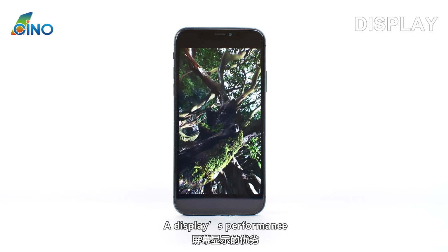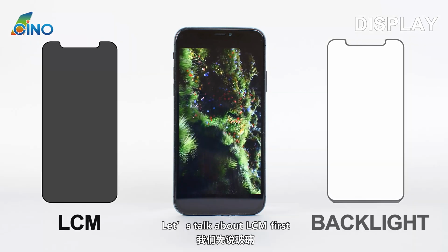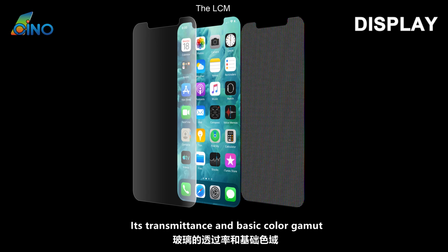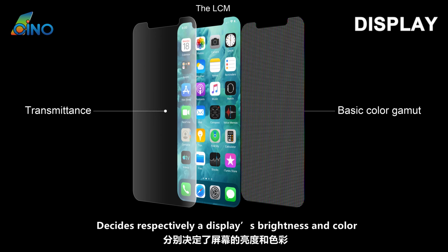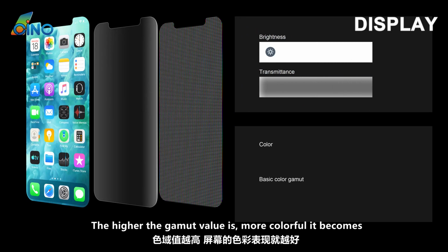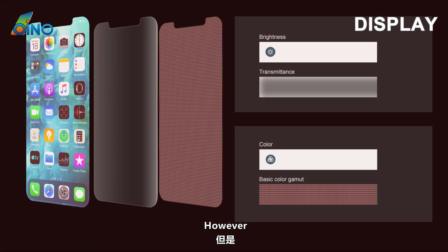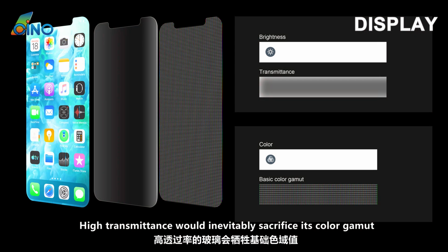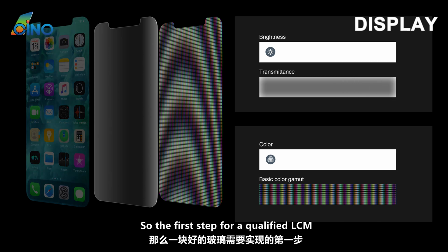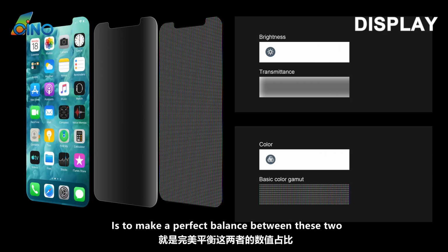A display's performance depends on two major factors: the liquid crystal module and the backlight. Let's talk about LCM first. Its transmittance and basic color gamut decide a display's brightness and color respectively. The better the transmittance is, the brighter it gets. The higher the gamut value is, the more colorful it becomes. However, high transmittance would inevitably sacrifice its color gamut, and vice versa. So the first step for a qualified LCM is to make a perfect balance between these two.